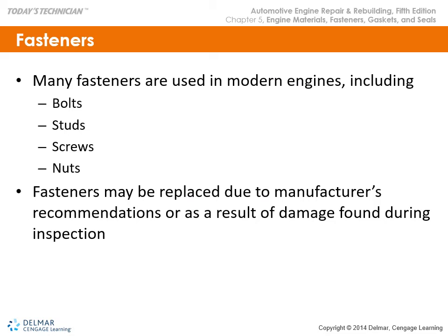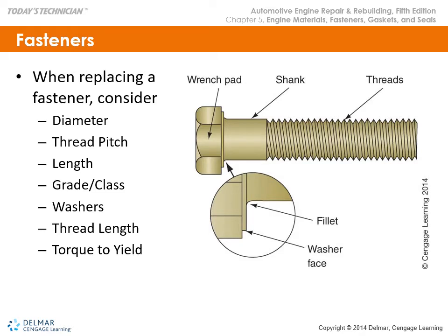Bolts, studs, screws, nuts, fasteners may be replaced due to manufacturer's recommendation or as a result of damage found during inspection. So you want to make sure that your fasteners are perfect for the application. Diameter, thread pitch, length, grade, and class is essentially the strength and the hardness. Washers, thread length.